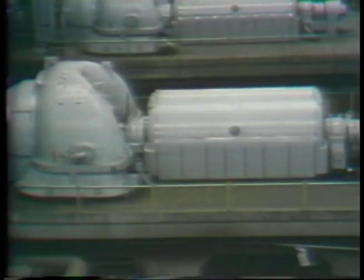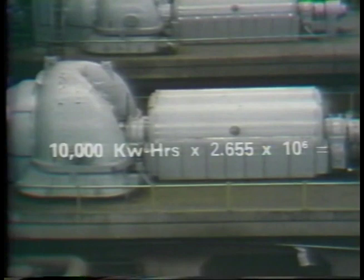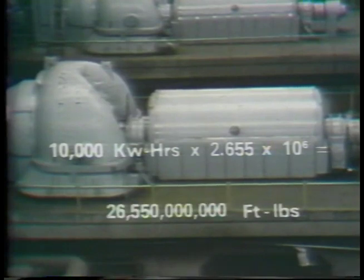Well, to give you an example of why kilowatt-hours are easier to use, let's figure the output in foot-pounds of a generator rated at 10,000 kilowatts. To do this, we multiply 10,000 by the conversion factor, 2.655 times 10 to the 6th. And we get 26,550,000,000 foot-pounds. Well, as you can see, it's a lot easier to talk about 10,000 kilowatt-hours than it is to talk about 26,550,000,000 foot-pounds.